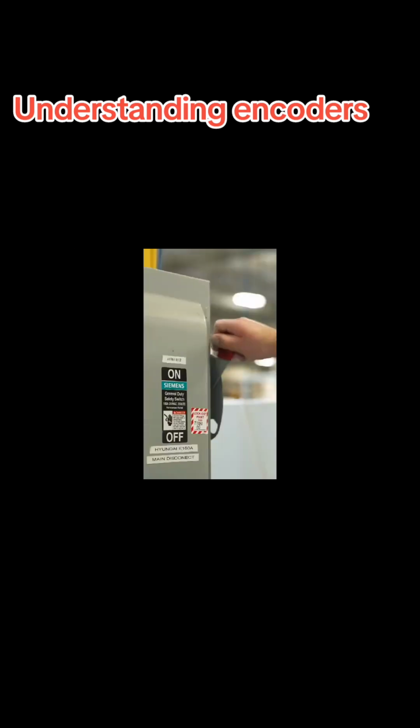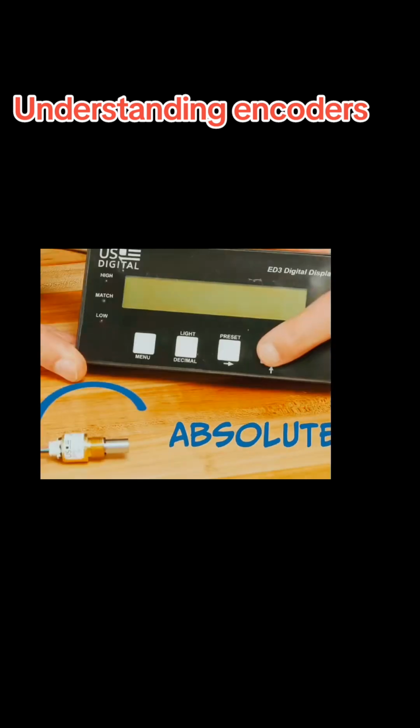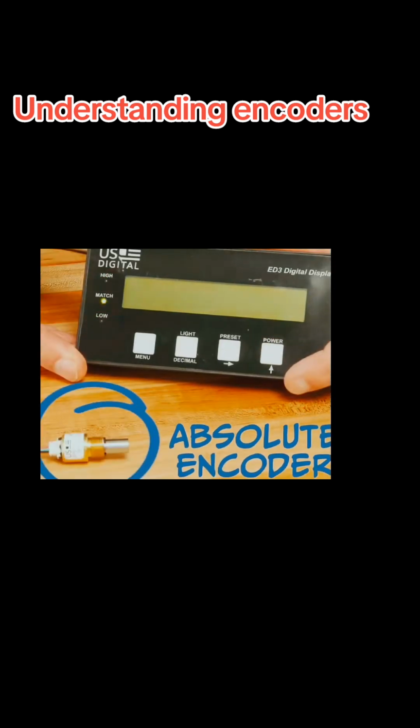Okay, now let's talk about the difference. Imagine there's no power. With an absolute encoder, when there's no power, the encoder has already captured a certain position and direction. When power is restored, the absolute encoder is designed to give you the exact same position, direction and count where it was. No data is lost.